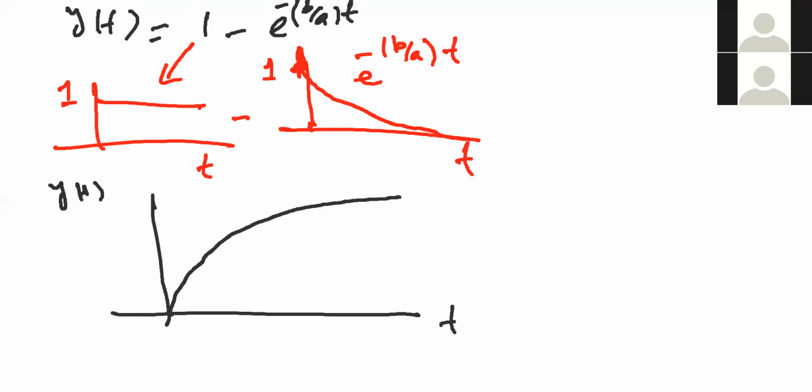And then you have the steady state response like this. So overall, it will be equal to 1, and then it is an exponential rise function. You see that the pole at 0 is giving you the steady state response. So this is equal to 1, so it will not go beyond 1. And the pole at any other point is giving you the transient response. So this is the transient state, and this is the steady state.